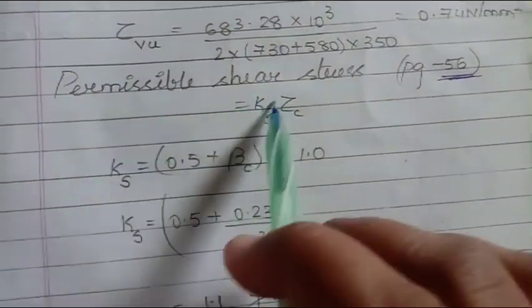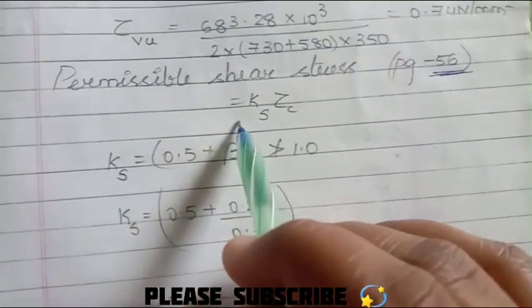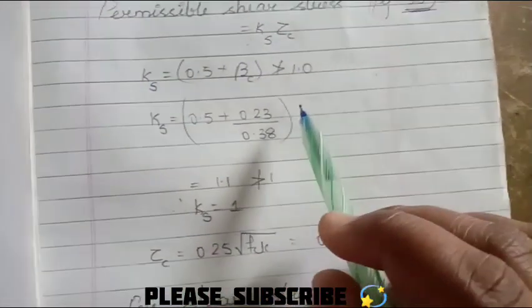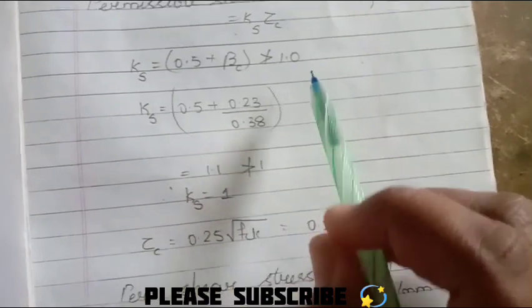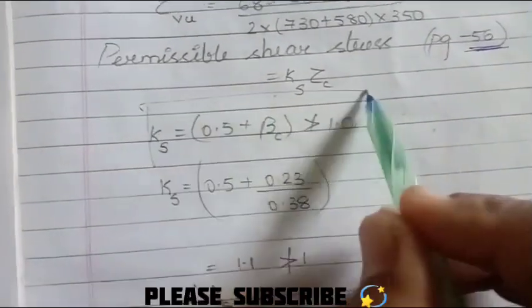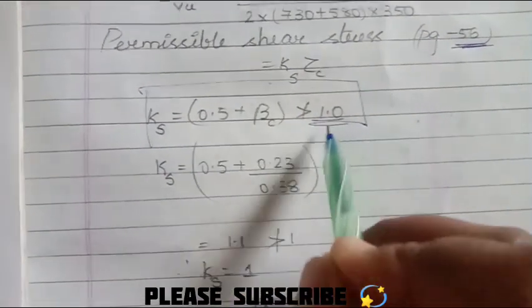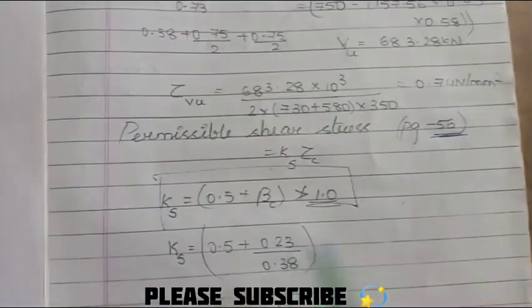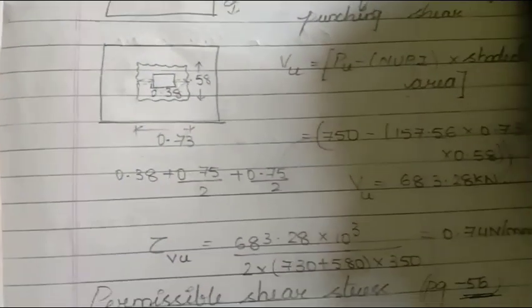See here, the permissible shear stress, we have this formula: some factor Ks multiplied by tau c. Whenever we are talking about beta c, remember this Ks shouldn't be greater than 1. If it is greater than 1, take 1. I will show you this diagram.